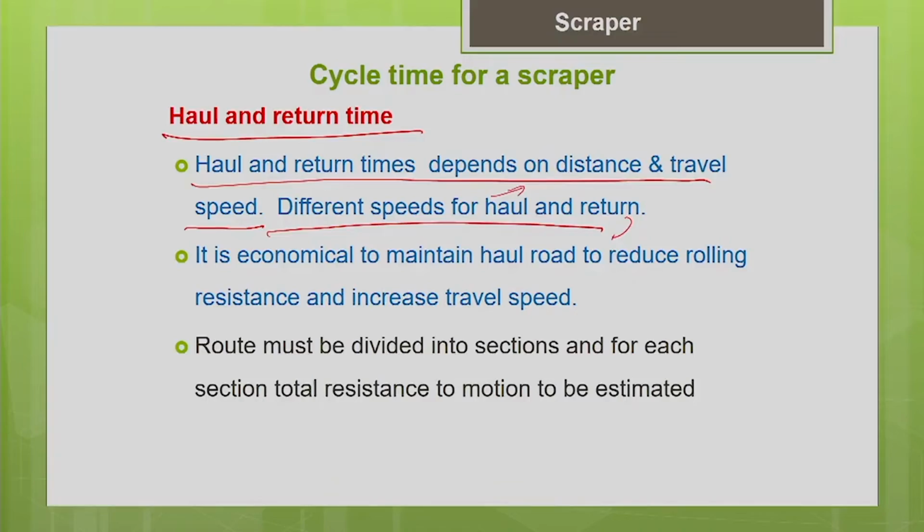All these things need to be done carefully. Whatever effort you put into maintaining your haul route will help in reducing the cycle time of your machine. It will help in reducing the haul and return time, and that way it will improve the productivity of your machine. So it is economical to maintain the haul route.